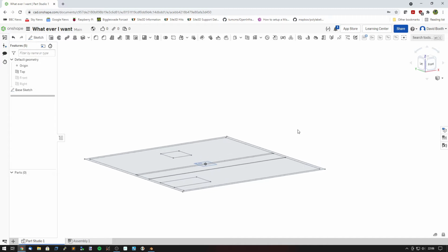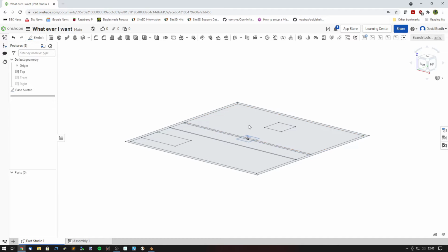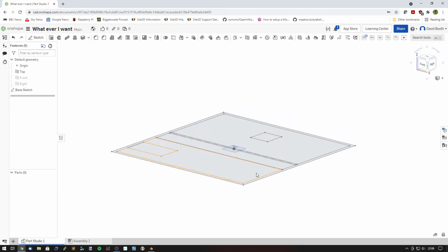If you're doing laser cutting or any kind of CAD, you can export these things right now. I can actually go in here and right click and hit export. I believe there's an export as DXF DWG. So this is quite a nice way if you're trying to design something, you can do your sketches and export your sketch out as a DXF or DWG.